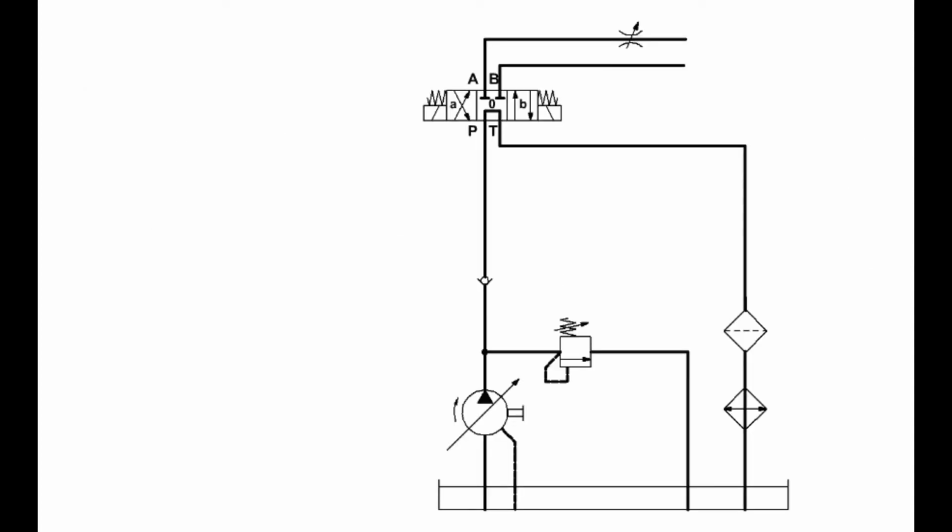We can now use the components of the energy control functional group to extend our hydraulic system as follows. A check valve positioned at the supply output ensures that flow continues in one direction only. This prevents fluid from flowing out of the hydraulic system and into the pump after the pump has been switched off. A 4x3 directional control valve is installed to alter the direction of flow.